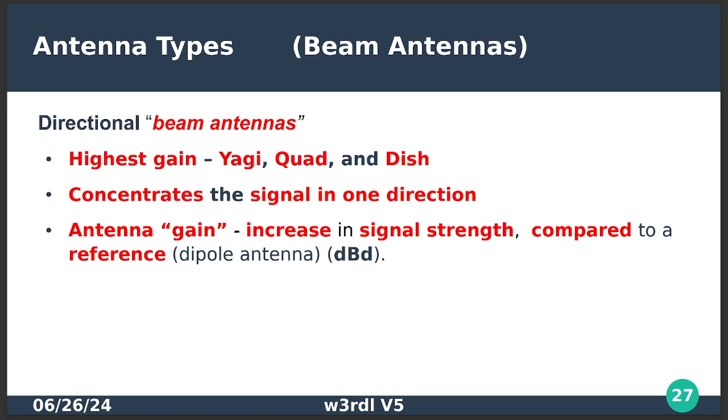You'd be surprised how simple that LNB is when you open it and look at it. Because when I was doing DirecTV installations, I thought that would be a really complicated technical thing inside there. It's not. It's an open tube that the energy goes into, and at the end of that tube, there's a tiny little antenna, and that's it.